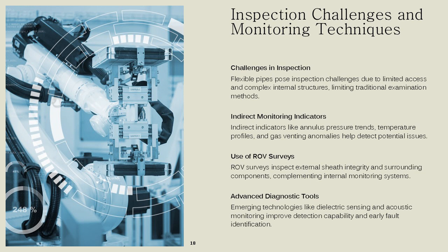Advanced diagnostic tools, including dielectric sensing and acoustic monitoring, are emerging to enhance detection capabilities. Despite these innovations, uncertainty remains, requiring conservative interpretation of data and robust contingency planning. Effective integrity management combines continuous monitoring with risk-based inspection intervals, ensuring timely interventions and sustained fitness for service.